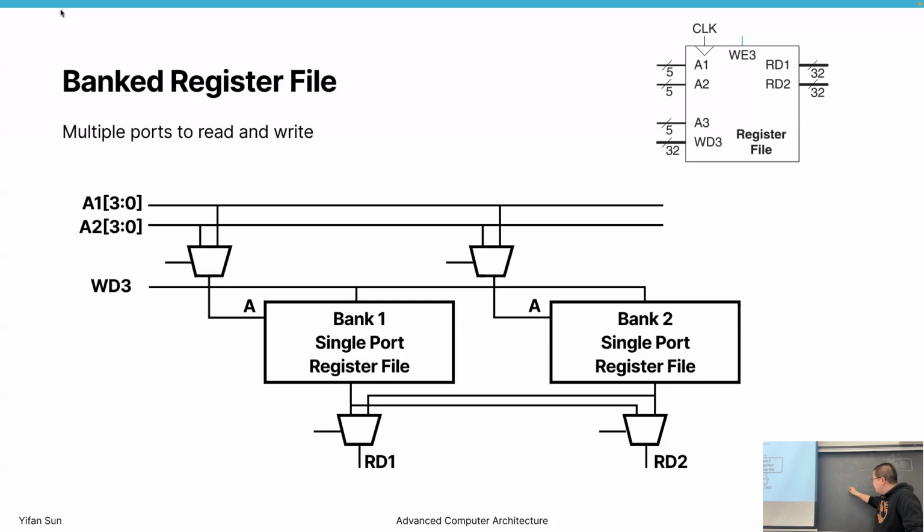So when we're reading from V2, we're actually reading from 32 registers. Although they are all named V2, they're for 32 different threads. So we're reading for 32 threads. In that case, because there are 32 threads, they have 32 sets of banks. So if it's a 4-bank register file, it's actually 4 multiplied by 32. They actually have 128 banks.